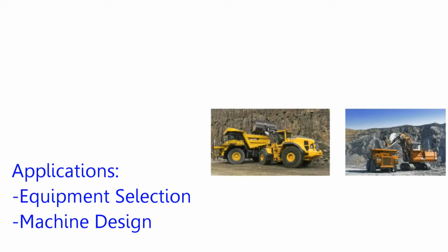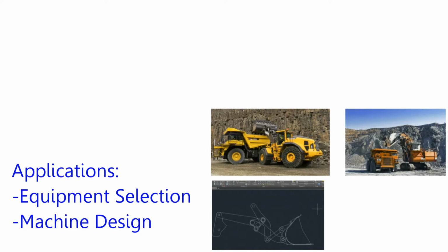Using standard pass-match, some mining companies have found after the equipment selection process is complete that they're not meeting their expected payload capacities. We can use loading simulation to close this gap, since we're able to include the mine's specific application details. And we're also able to use loading simulation to design application-specific equipment like dump bodies, for example.